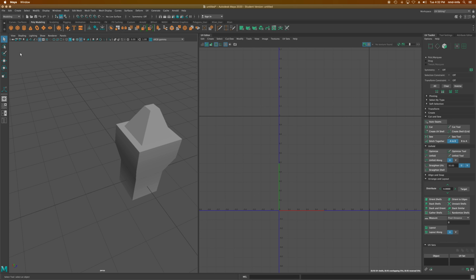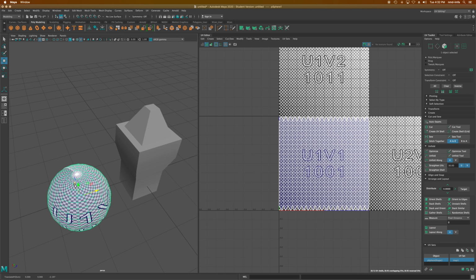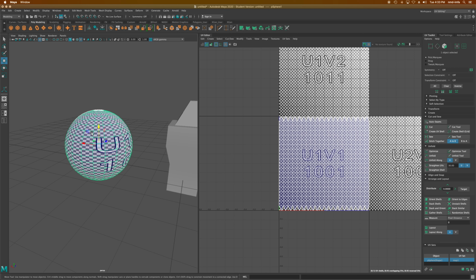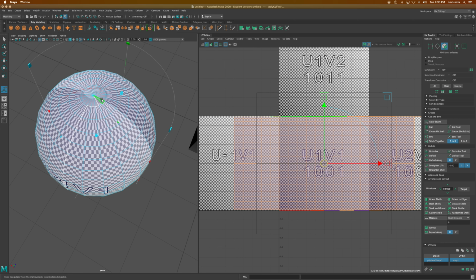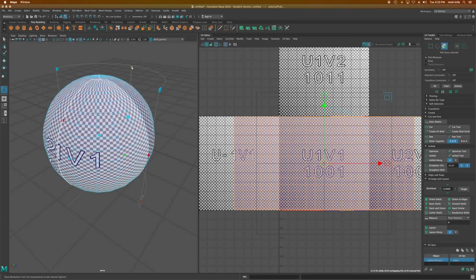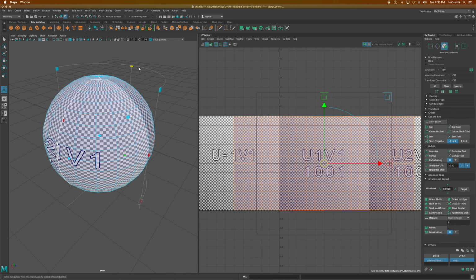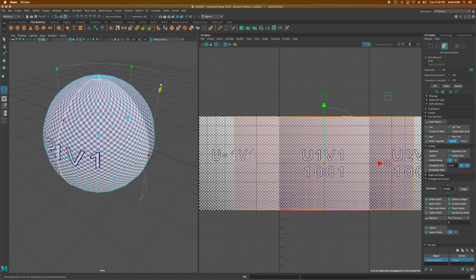Let's bring a sphere in. Whoop, wrong arrow. And just right off the bat, you'll see over here on the right, I have this weird picket fence UV. But if I go to my UVs here and I choose cylindrical, that warps them correctly. It kind of brings them to a point up at the top, but it gives me this cage again where I can decide how much I want to repeat this pattern. Do I want one big one stretched over it? Where do I want the rotation of that to begin and end? So some nice tools there if you're working with basic shapes, right?